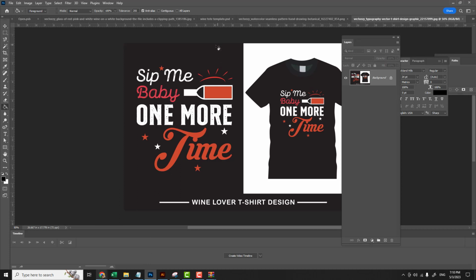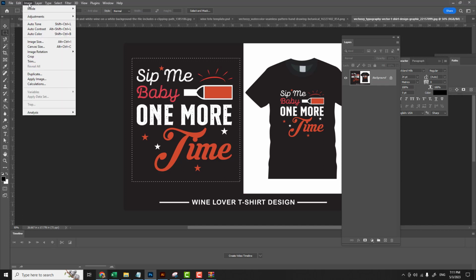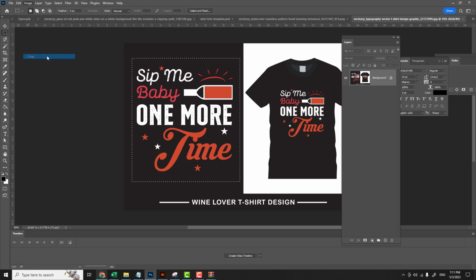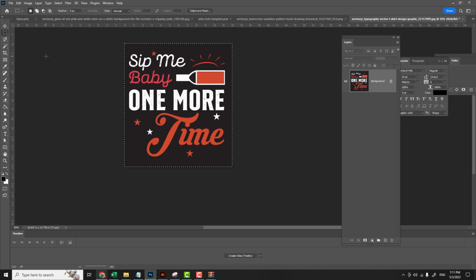Okay, so this is the part that we want. So I'm going to crop this out first of all. I'm just going to get my rectangular marquee tool and I'm going to drag a rectangle around it. Okay. I'm just going to go in here on our image and crop. Okay, the next thing I'm going to do is try to get rid of the black. But I don't want to get rid of the black on the inside of the letters.